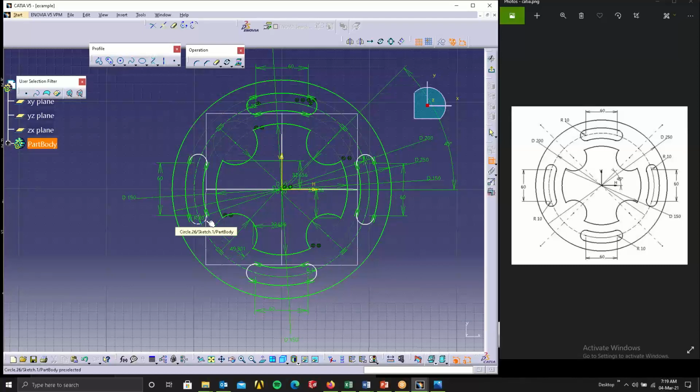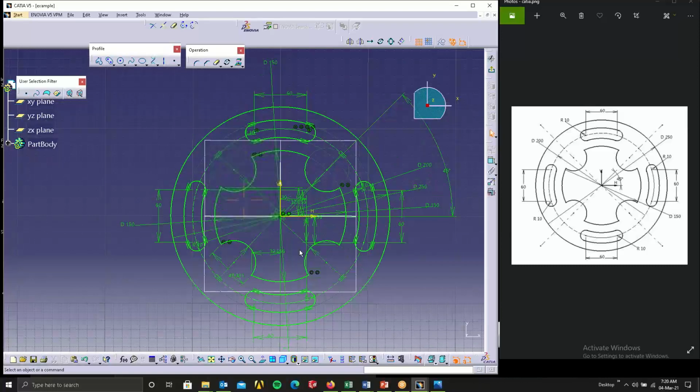Now all that remains is this radius, still is already there. So again this thing will be with respect to the horizontal or vertical distance. So you can see within a few steps we could constrain the entire thing. Always make sure your constraint conservation is turned on when you're doing the rotate command, or else whatever trouble we are facing, we had to do every single thing. Even a little movement, this also would have shifted. So here tangencies, everything is applied, all the constraints are conserved. Understood? Okay, this is how you do it.